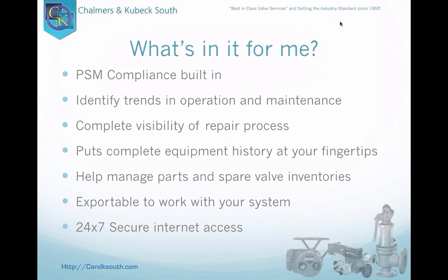It helps you identify trends in operations and maintenance. I'll show you some more of the tools in there, but for example, it doesn't have to be a safety valve, but let's say it was a safety valve and you had a batch of those come in for repair, and you can see quickly that 80% of those failed the initial pretest. Well, that's clearly an indication of what you need to do as far as maintenance. You probably need to shorten up that cycle, because if 80% of them are failing pretest and one of those needed to lift, then you would definitely have an issue. However, if you also see that 99% of them are passing that pretest, it may be an indication that you can extend that.